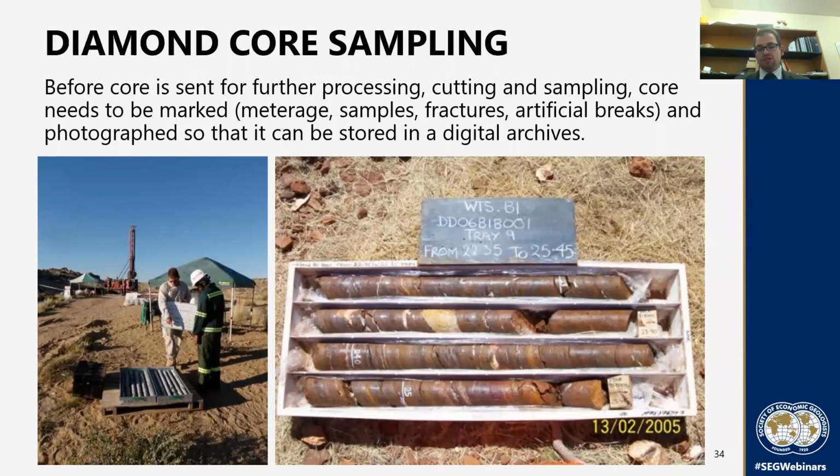And of course, if you do a geotechnical investigation, you need to assess how many open or closed joints and fractures you have. Now, if these artificial breaks that are introduced after the drilling process has finished are not marked correctly, you might get erroneous results during geotechnical aspects of the drilling. So keep this in mind.